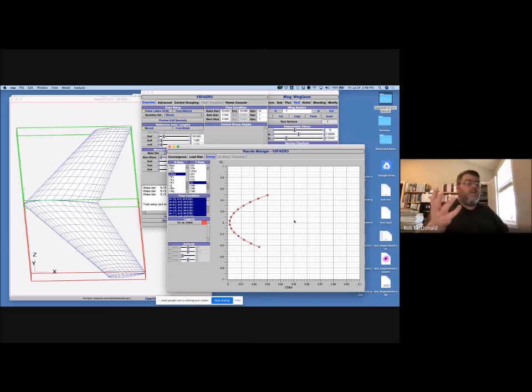And from the aerodynamics and aircraft performance standpoint, those are two different speeds. Any airplane will have a best range speed and a best endurance speed, right? The best range speed is always going to be a little faster. But any airplane will have those two speeds, whether you want it or not. It's just the way the physics works. And what determines that is that they're different points on the drag polar.